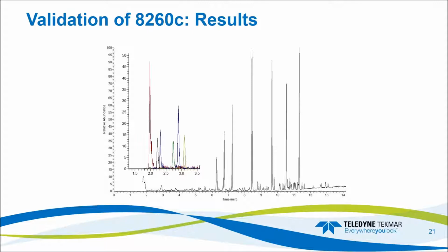So here's an example of a chromatogram that we're able to collect. I believe this is a 0.5 ppb or maybe a 1 ppb. But for the first 6 gases separated out here by their target ions, we see that we have good intensity of target ions. We have nice separation. So again, the nitrogen purge is not going to affect our chromatography.